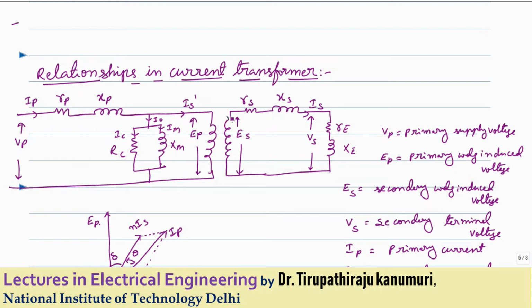Getting it? So now coming to the secondary side, the winding will have the resistance, so that Rs will be there. Similarly, your ammeter load, whatever the load is there on the secondary, care will be taken that it will be mainly a resistive load only. So always it will be taken care that the secondary side burden is mainly resistive.